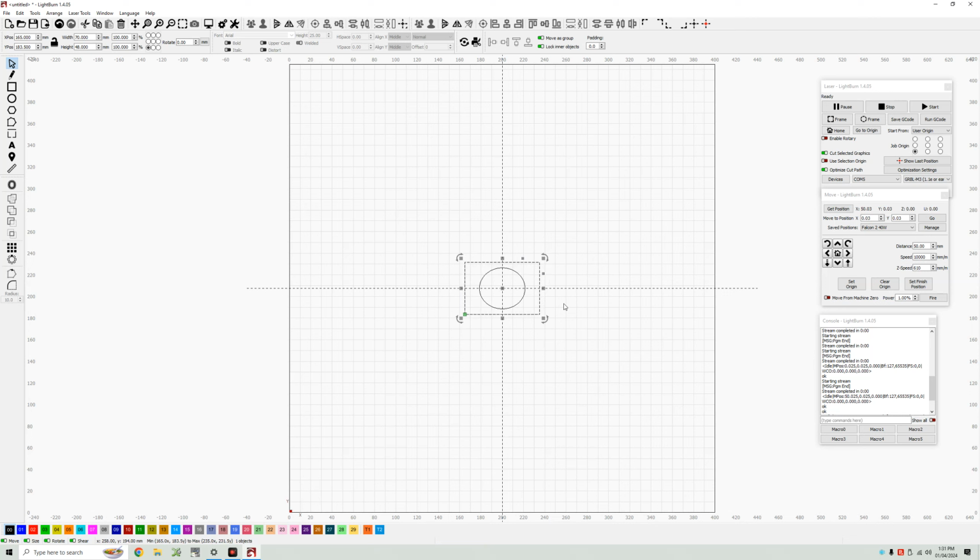Now I don't. It's always going to start right there where I defined my user origin, which is just shove something up against the alignment rail and print it. And in real life, how it's going to print is going to look like this on the wasteboard. Well, not this, it will actually be centered, but before I would have to group them and then put them down there to center it. Just not necessary now. I can leave it right there, and it's going to start there on my work surface.